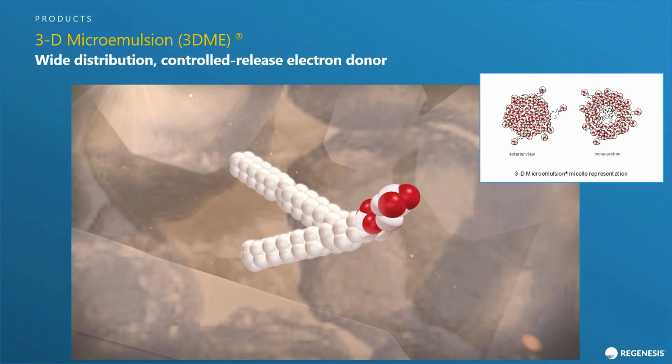So they can distribute very long distances, greatly reducing your drilling cost in fractured bedrock sites. It's also engineered to be appropriately soluble, so it's not going to wash out either. And once injected, it will continue to release hydrogen for up to 5 years. So you can create a really stable environment with this technology.